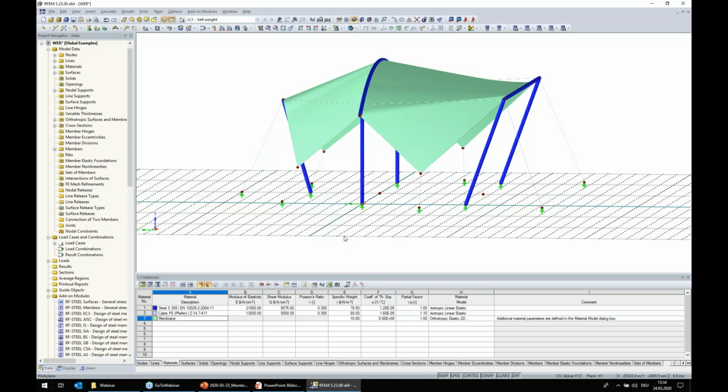When we expect that the program creates such nice homogeneous shapes, we have to force the program to calculate this shape by some definitions, for example pretensions, and this process is named form finding. So the program can calculate or evaluate the place of mesh nodes according to some tension definitions in the membrane, according to some force or deflection definitions in cables, and gives us a shape which is under tension for further calculation of some basic load cases like the snow load case.